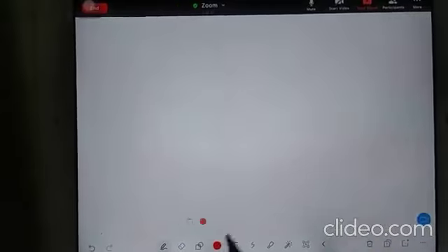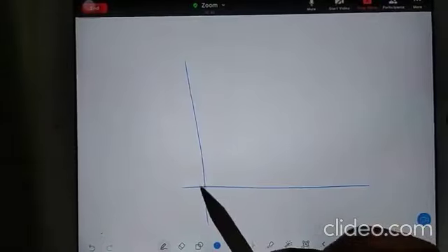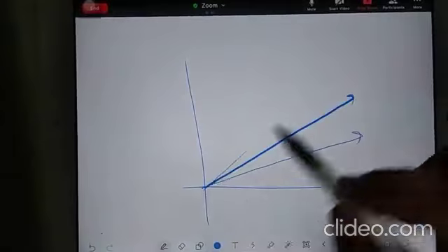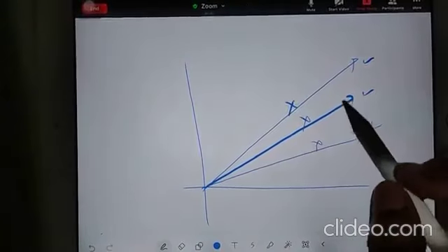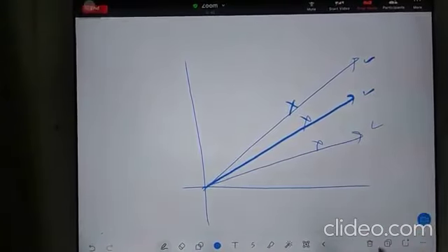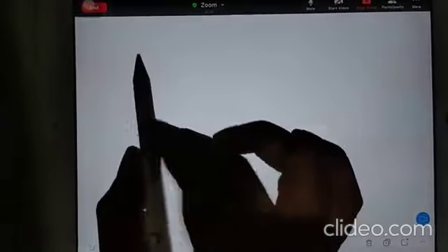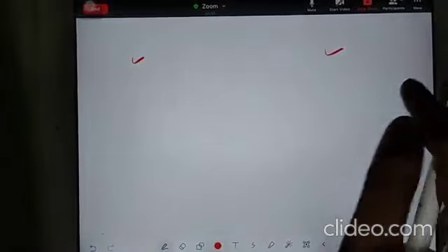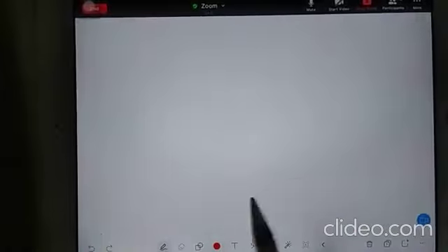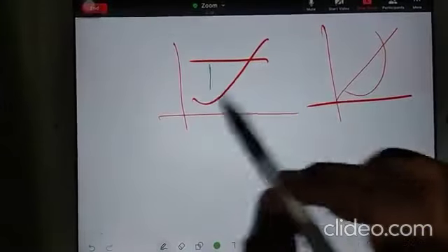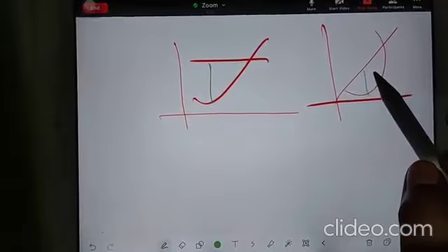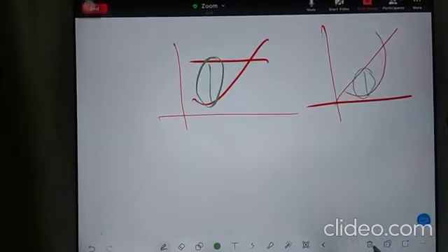And one thing is very clear. If you want to fly at this angle or this angle or this angle, it depends on what kind of aircraft you are flying. So angle will not disturb you when you talk about drag. But both the engines, jet engine and propeller engine, have issues with available power and excess power, according to the gap between available and required, like this gap and this gap. So we will discuss our climbing according to the gaps for both the engines.